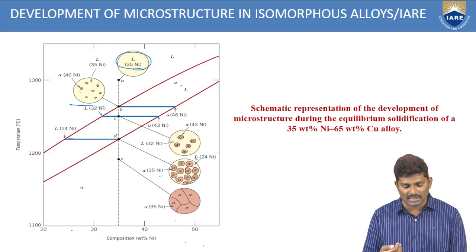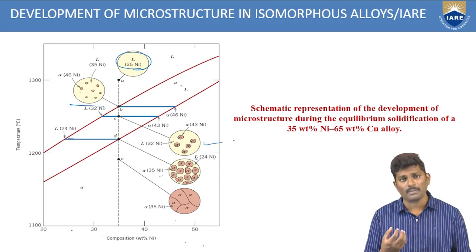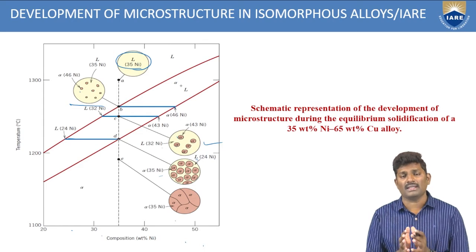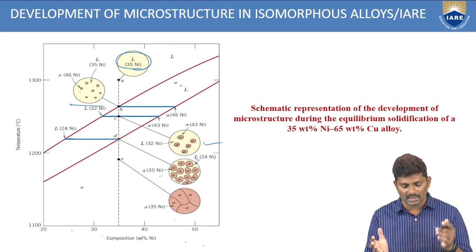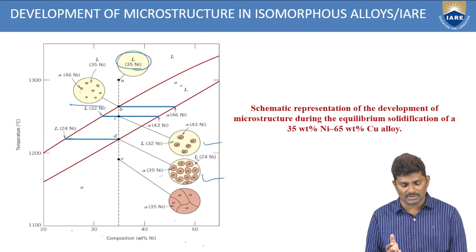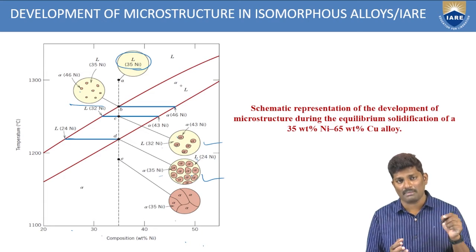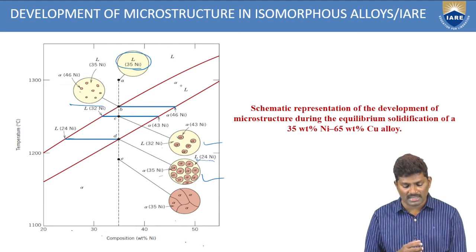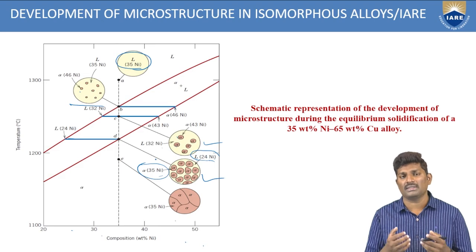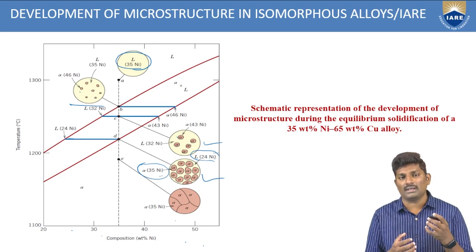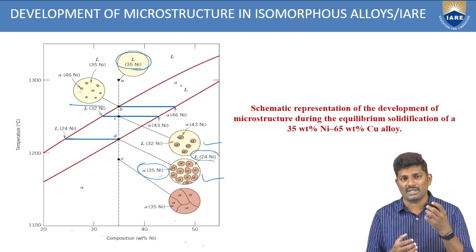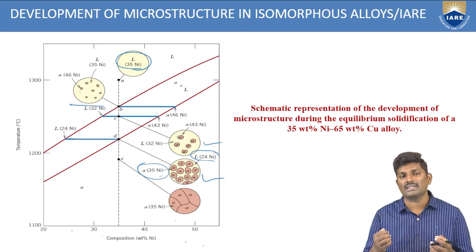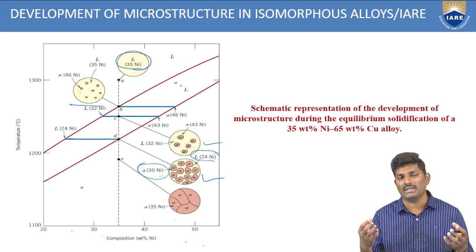If you still reduce the temperature at point D, there is an increase again in the solid particles. So that's why you can see the increase. But there is some gap there. This gap represents the other phase. What is the other phase? The liquid. That's why the liquid percent is getting reduced and the solid percent is increasing. This refers to the reduction in the temperature. Because of the reduction in the temperature, the liquid is getting absorbed and the solid is being formed.